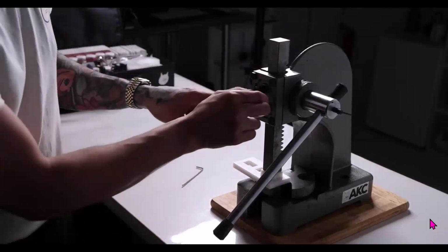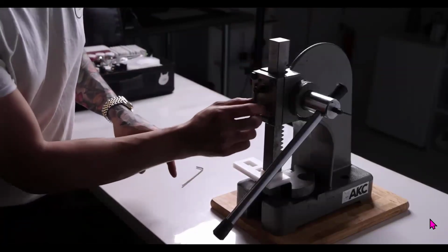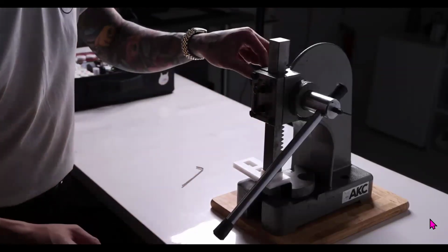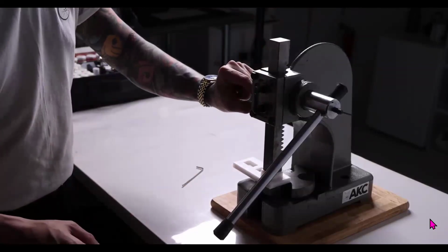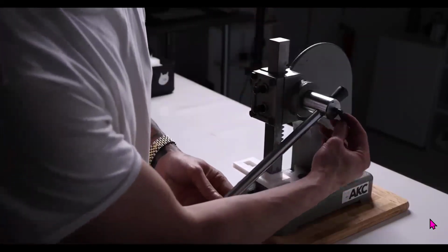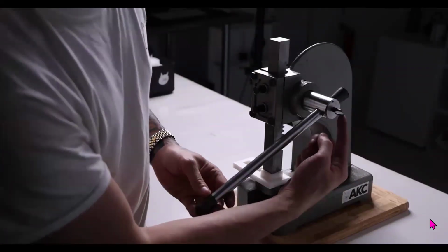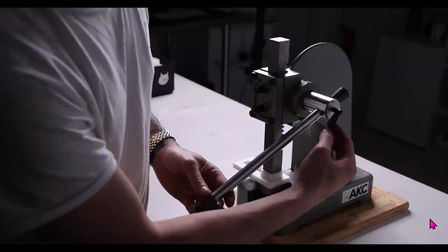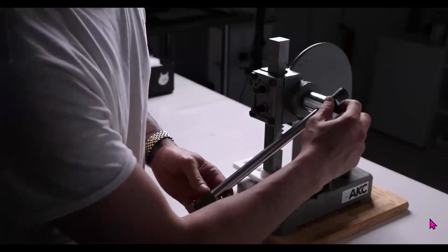Next, you will notice there are 2 screws in the front and 2 screws on the side. These parts control how tight the middle bar is. If you find that the middle bar starts wiggling, that means it's too loose. All you have to do is take your finger and tighten those screws a little bit and you're all set.